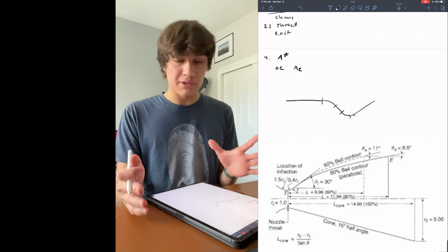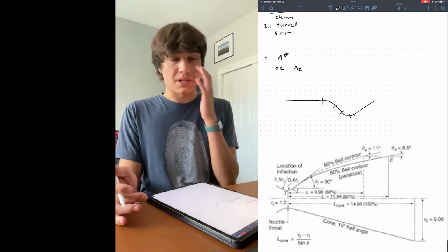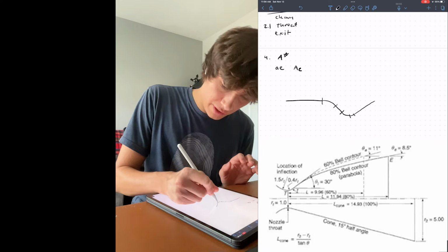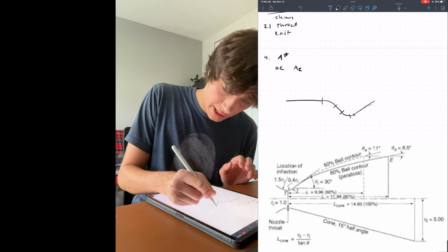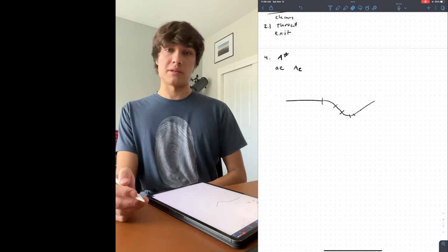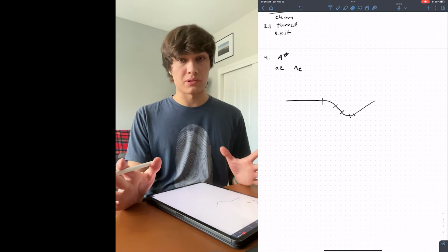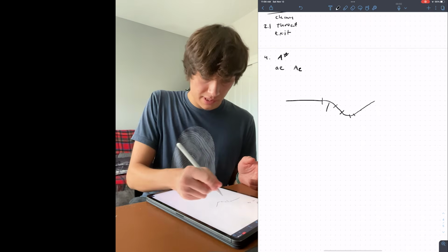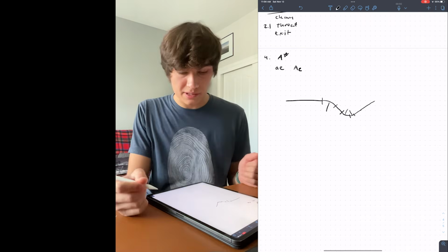At first, I recommend using a conical nozzle because at low pressures, the efficiency gains that you'll get from a parabolic nozzle are going to be very slim because it'll look basically like this and there's very little difference. But you can read up on parabolic nozzles in Sutton as well or some other text. Remember, parabolic nozzles are a mass optimization. And then standard ratios for this and for these two can be found in Sutton as well.